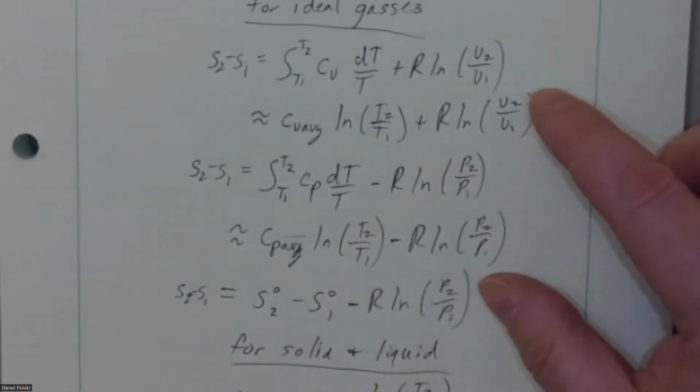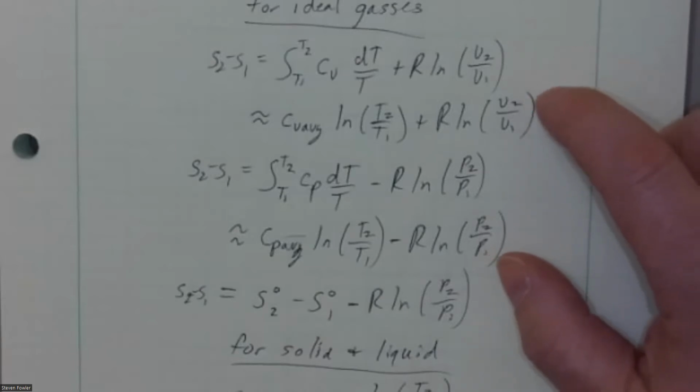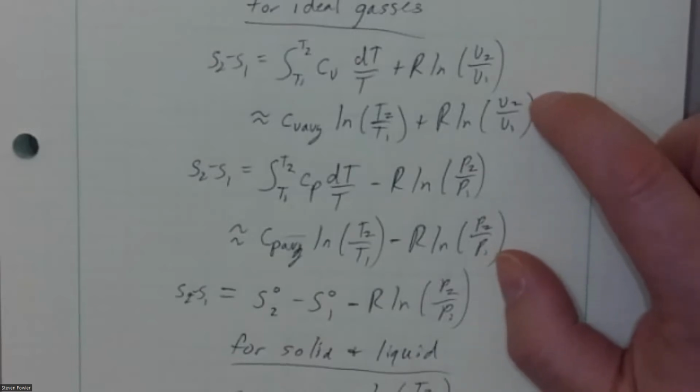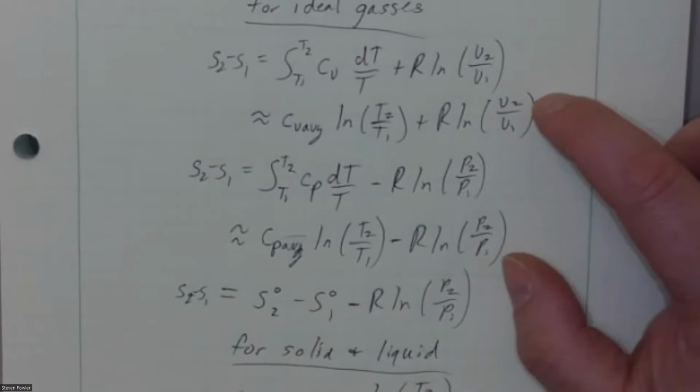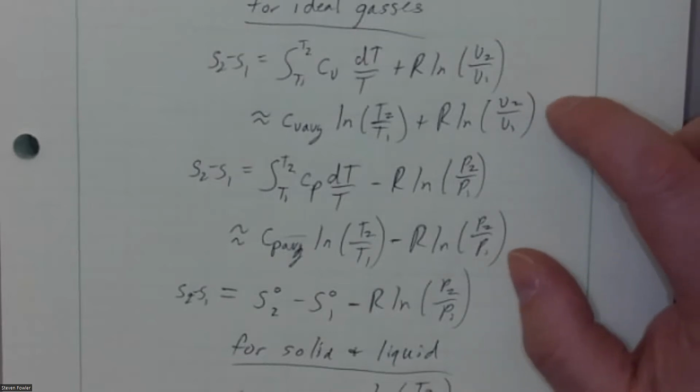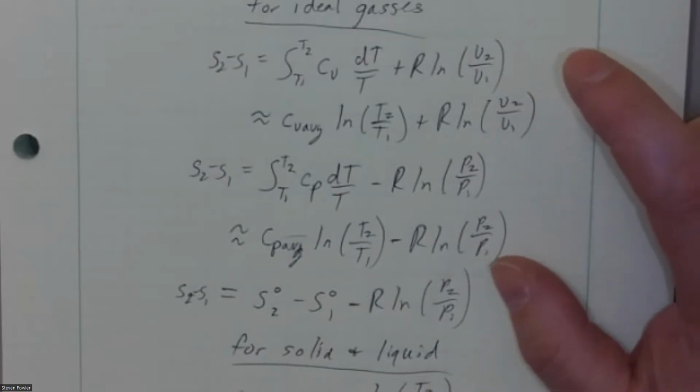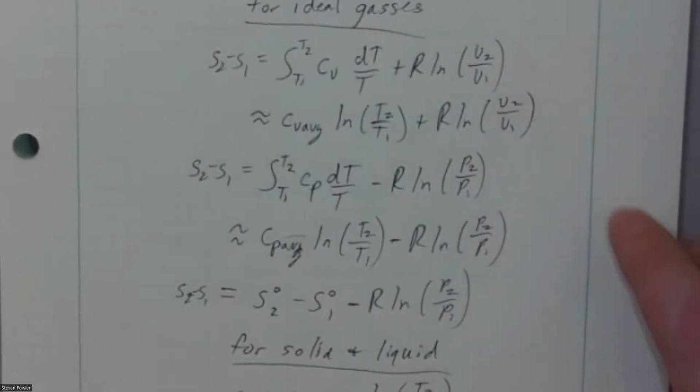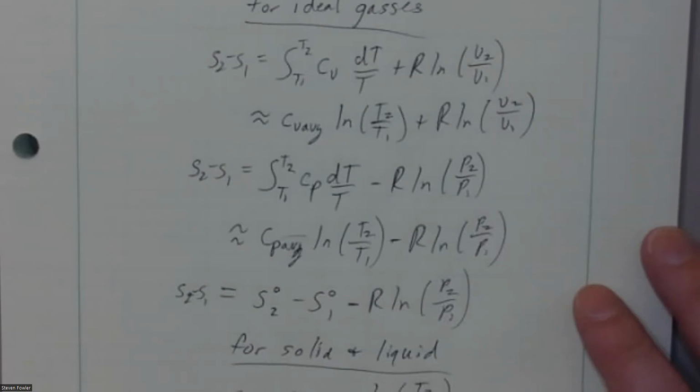Well, it's more about which of these properties can you get, right? The question is which one of these is better for which, and it really comes down to which of these properties are more realistic. If I've got a control volume, I'm probably not going to know the specific volume of the fluid coming through. I'm going to have to estimate it, which is possible. But I'm probably going to be able to put a pressure gauge at the end of it, a lot easier than I could either take a sample and measure a specific volume or somehow approximate a specific volume.